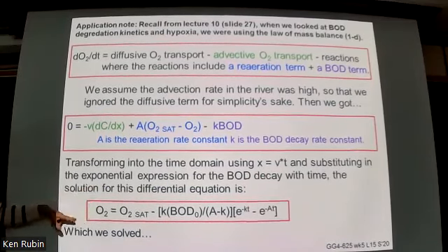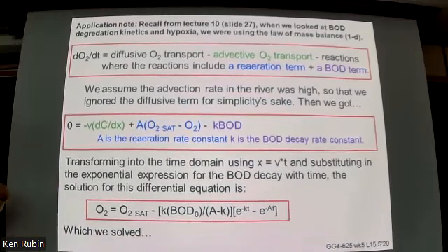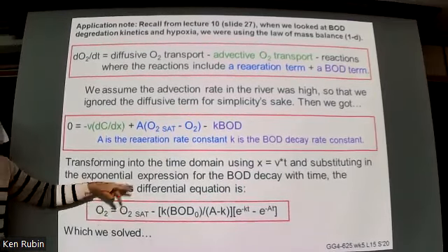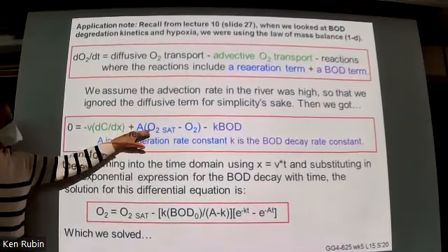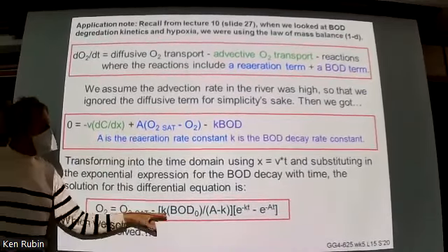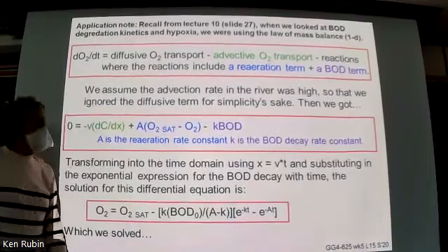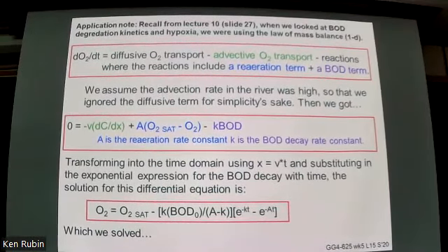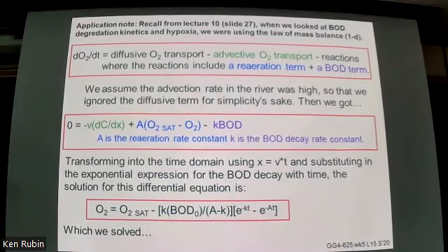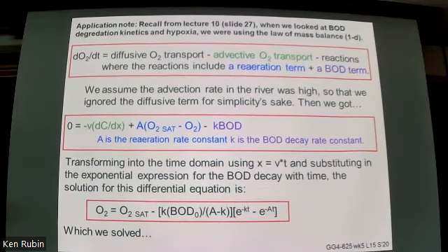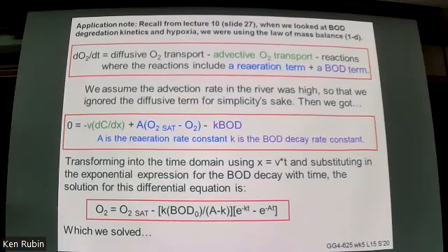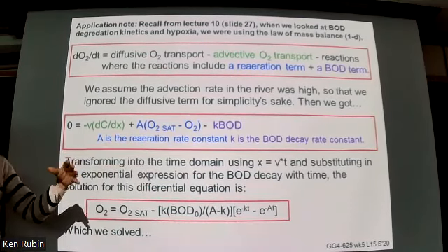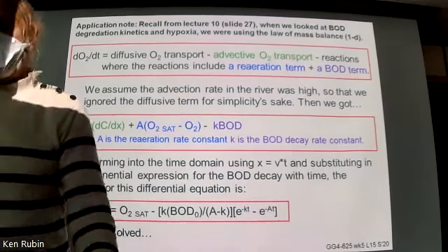But we wrote this equation out, which told us the oxygen at a certain time was the amount of saturation, which is what exchange with the atmosphere is trying to do, minus the reaction terms, which look like that. And so that's a version of the diffusion advection equation. What's missing from here is diffusion, because in this particular case, the amount of diffusion that happens is small compared to the fundamental process that we're studying. You could add it in there, but it wouldn't change the result.